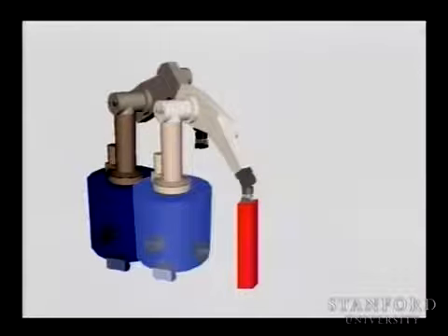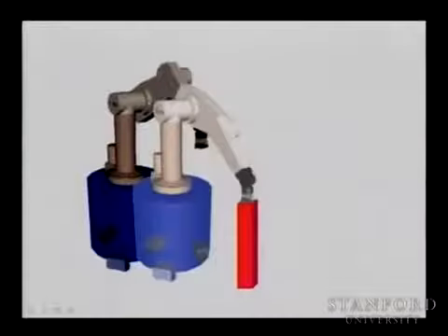But the problem with this is the fact that if you have redundancy. So what is redundancy? Redundancy is the fact that you can reach that position with many different configurations because you have more degrees of freedom in the system. And when you have redundancy, this problem of inverse kinematics becomes a really difficult problem. But if you solve it, then you will be able to say, I would like to move each of those joints from this current joint position to this joint position. So you can control the robot by controlling its joint positions and by creating trajectories for the joints to move, and then you will be able to reach that goal position.